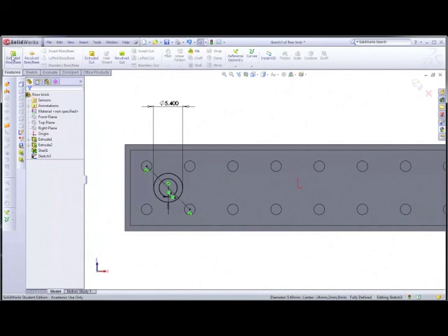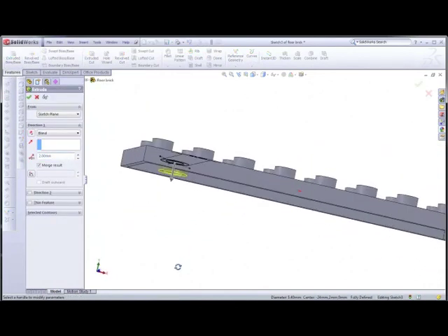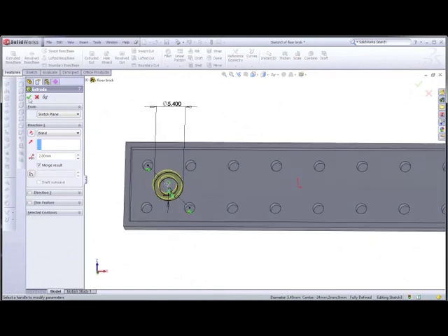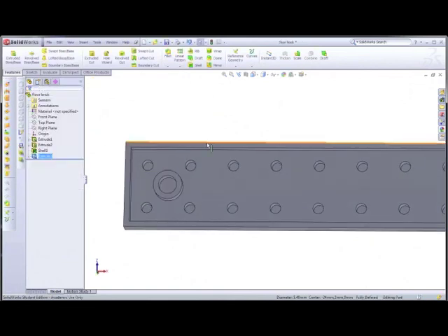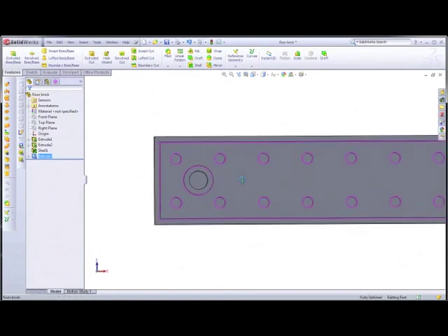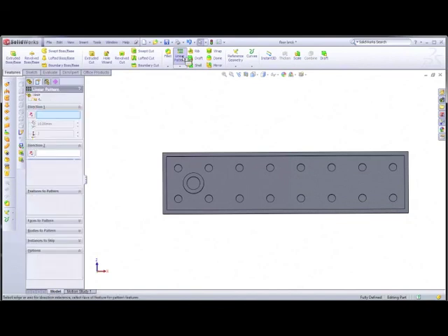feature, extrude. And that we can see it's now gone to 2 mil. Right. So remember before we done a pattern within the sketch. There's also another tool which is linear pattern tool. So there's more than one way to do things within SolidWorks usually. So if we use the linear pattern tool now,